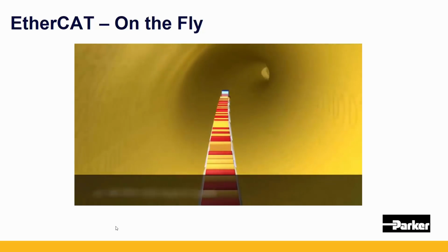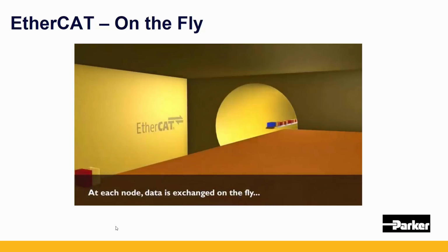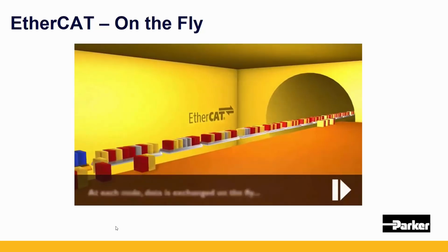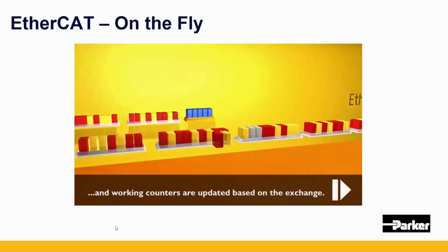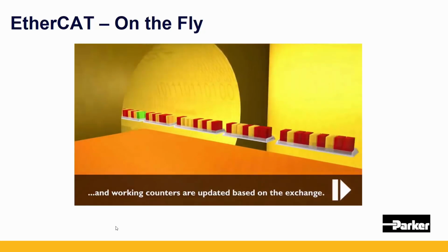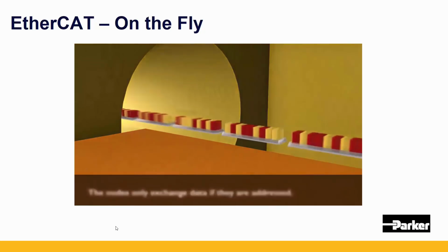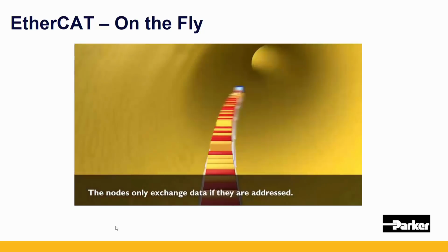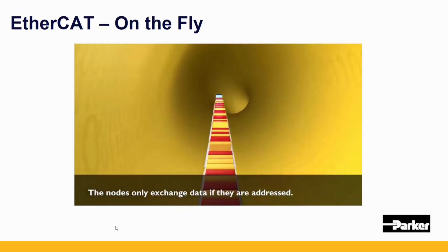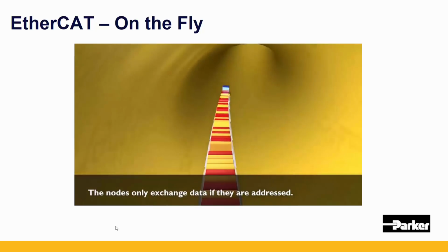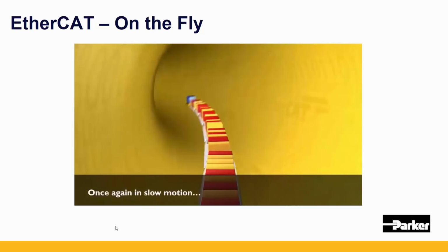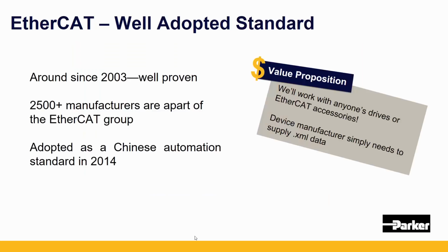It sends the train from the master, it goes the same exact route every single time, and then returns back to the station. So what you also get as a huge benefit is so much additional bandwidth for the data that you actually care about, since it strips off all the unnecessary layer of checksums and header information that are really not useful to Ethercat. But what it also does is, because we're using this train-like packet structure, that means that there's absolutely zero chance for collisions.